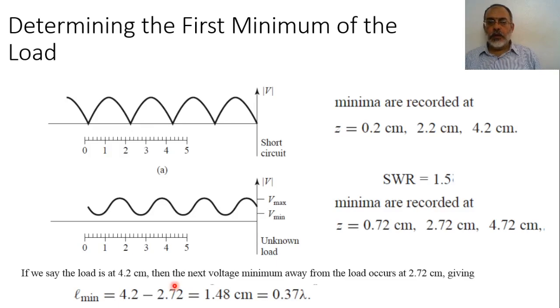Now we are going to determine L minimum and the phase. To determine L minimum, we select one of the minimum points of the short circuit and assume that this is the reference point.